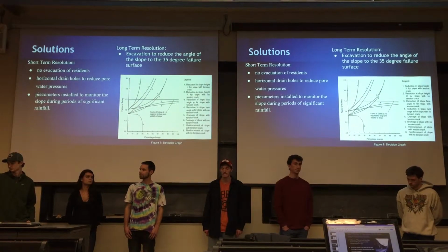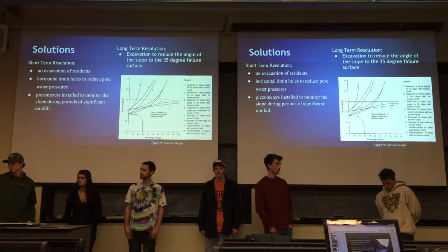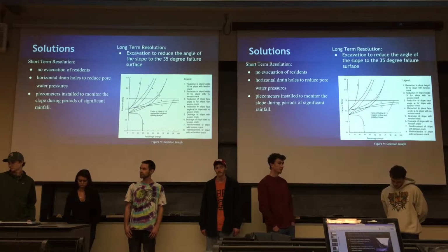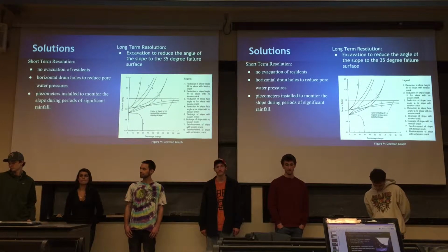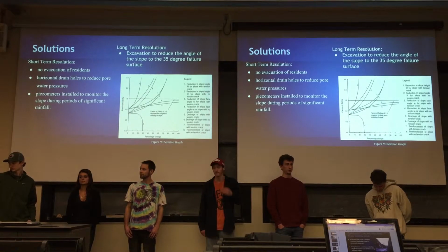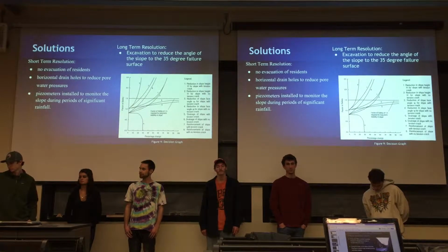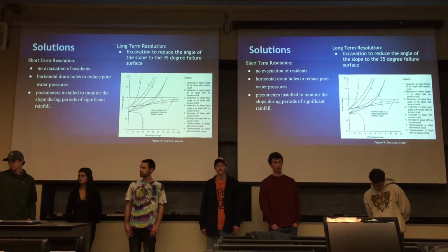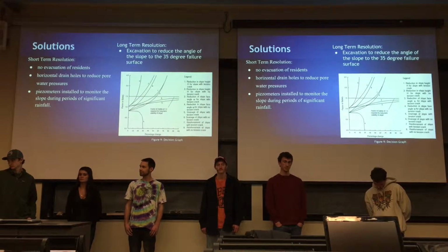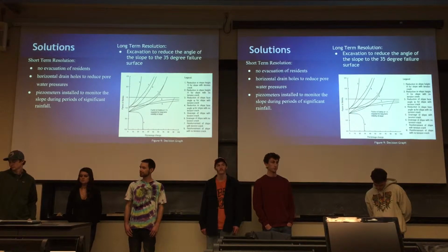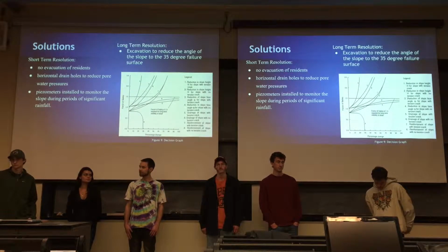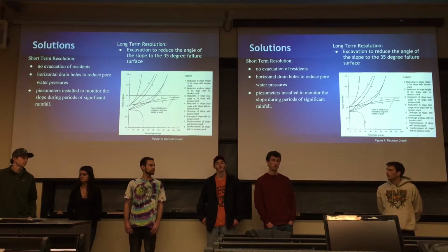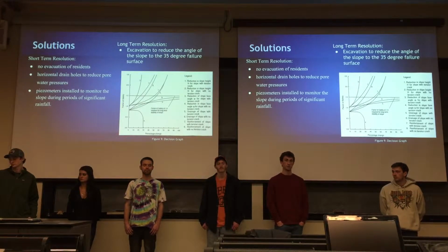So in the end, they had some short-term resolutions that were made. They decided that they didn't need to evacuate anyone, and also as preventative measures, they were going to drill holes in the side of the slope to remove some of the pore water pressure acting on the slope, and also they were going to install piezometers at the top of the slope to monitor the saturation of the soil during